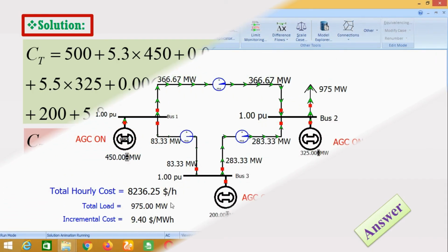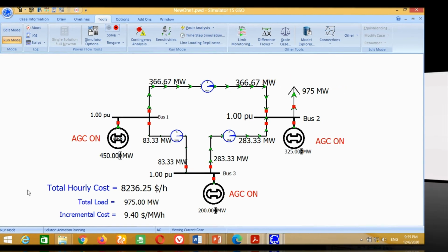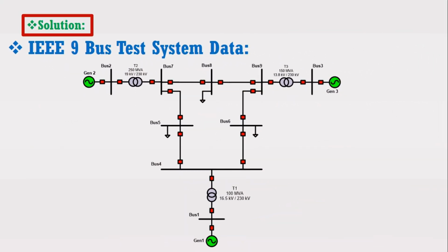Friends, in this tutorial I have discussed how to perform economic load dispatch including the generator limits in the PowerWorld simulator. By doing the same way, any power system can be designed in PowerWorld simulator and its economic load dispatch can be performed. I will strongly recommend all of you to take IEEE 9-bus test system with data and try it to build in PowerWorld simulator and perform its economic load dispatch.